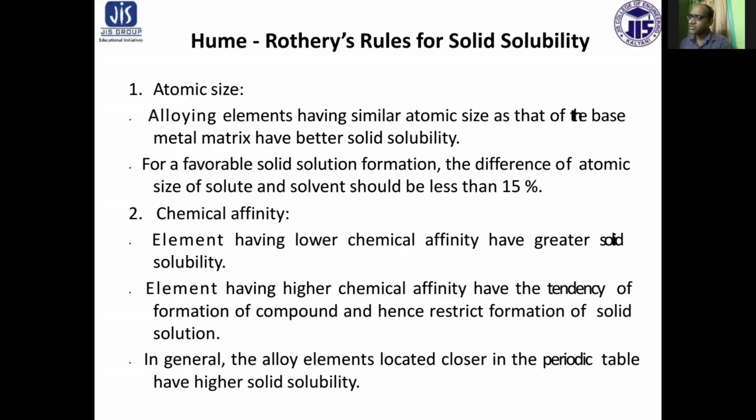With this, there are some other parts: some intermetallic phases also exist. When an alloying element is added to a given metal in such an amount that the limit of solid solubility is reached or exceeded, a second phase appears with the solid solution. The second phase may be another solid solution or an intermetallic compound.